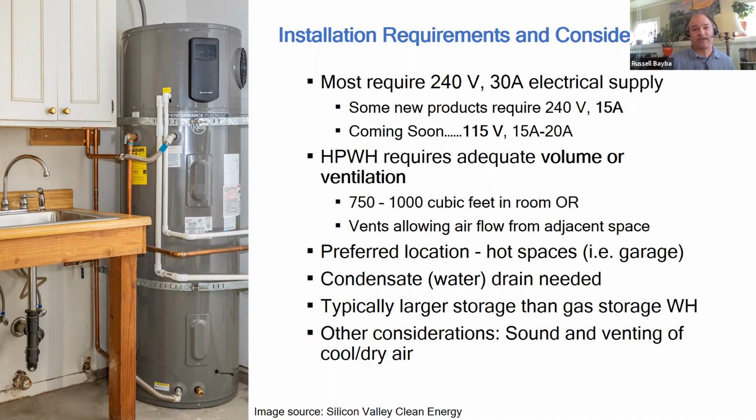I did see one application, more of a commercial situation, where they put it in a server room that heats up quite a bit. The heat pump water heater sucks all that heat out of the air and then dumps that cold air, essentially modulating that computer room. The vents can be adjusted, so it could be vented outside. It could be in a room that vented to another room.